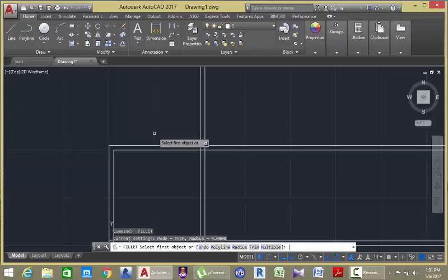This time around, you're going to select the Multiple option, but there is no need to type the full word. Look at the word with the blue color, which is also in uppercase. AutoCAD gives you the opportunity to enter just one letter in the option. That letter is changed to blue and uppercase, while the other letters are lowercase and black. So type M on your keyboard and press Enter.